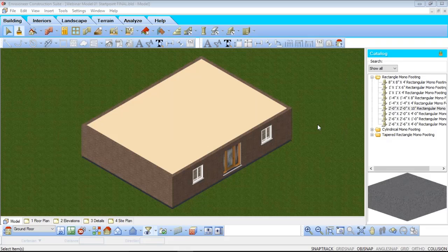Why is it so important? Well, building location settings determine all of the following in your project. They determine the relation of each story to grade level or ground level, the heights of your walls, the placement of your floors and your ceilings, the height at which doors, windows, and openings are inserted into your walls, and the framing specifications for your walls.